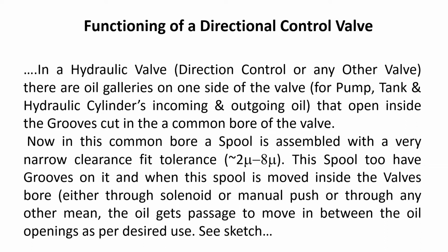In hydraulic valves, direction control or may it be any other valve, there are oil galleries on one side of the valve for pump, tank, hydraulic cylinder, incoming and outgoing oil that open inside the grooves cut in the common bore of the valve. Now in a direction control valve, oil galleries open only on one side, whereas in all other valves, pressure relief, pressure sequence, stackable flow control, there are oil galleries on both sides, because these valves have to come as a sandwich in a stack cluster on a power pack. So you'll see later on in the power pack sketch.